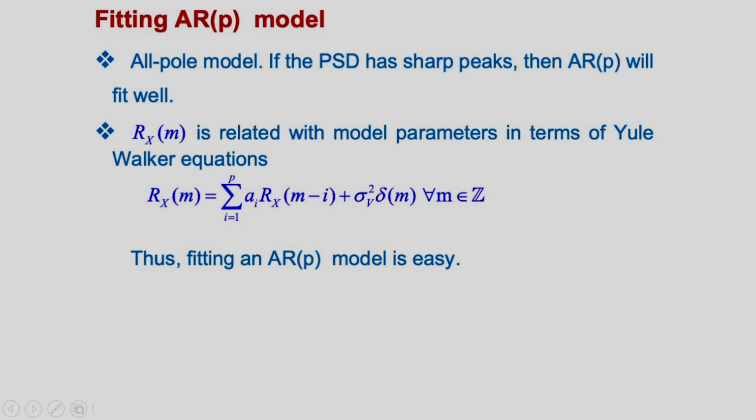Fitting an AR(p) model. Because the AR(p) model is an all pole model, if the PSD has sharp peaks, then the AR(p) model will fit it well. Rx(m) is related to the model parameters in terms of the Yule-Walker equation. We also know this is a linear set of equations, therefore solving this set of equations is easy. Thus, fitting an AR(p) model is easy.